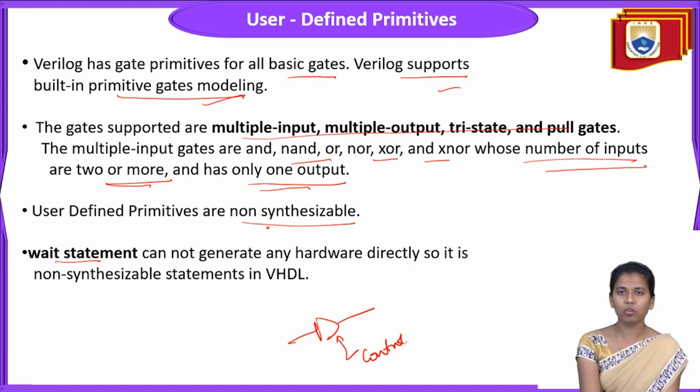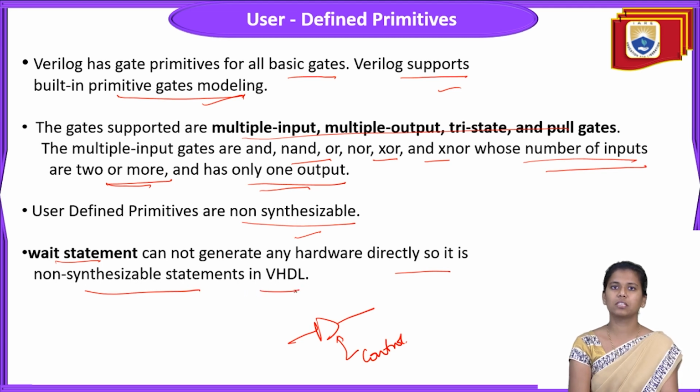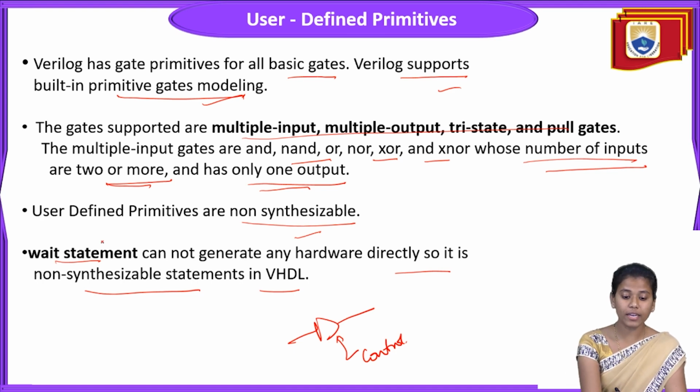To elaborate on what synthesizable means, wait statements cannot generate any hardware directly, so it is a non-synthesizable statement in VHDL. In this hardware description language, we are saying this via the wait statement.